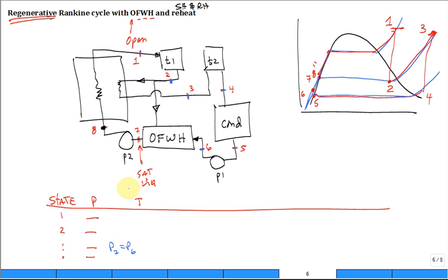How about the pressure at 7? It's just coming out. So guess what? The pressure at 2, the pressure at 6, the pressure at 7 are all the same. Then we go, that's an intermediate pressure. Then we go to pressure at 8, that's back to high. True? So if you march around and get your pressures right, it'll really help you. And then go ahead and get your enthalpies. If you know how to fix the states, it's just adding just a little more complexity, but we want saturated liquid coming out of the condenser, and we want saturated liquid coming out of the open feed water heater.